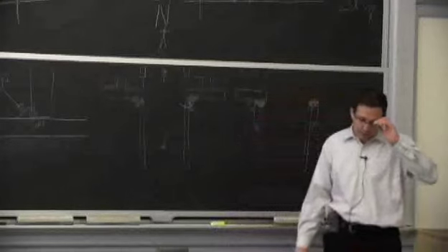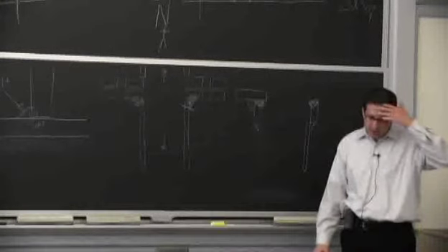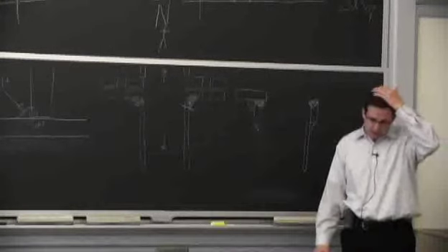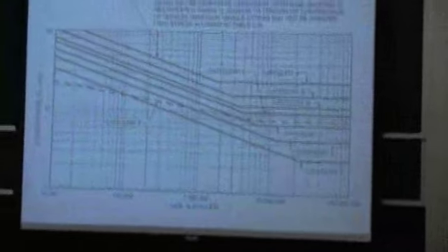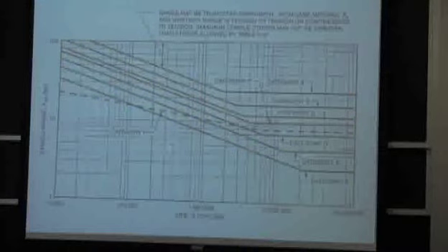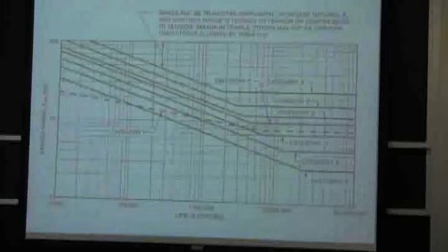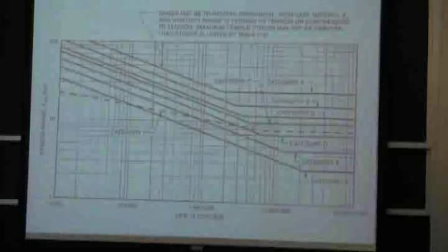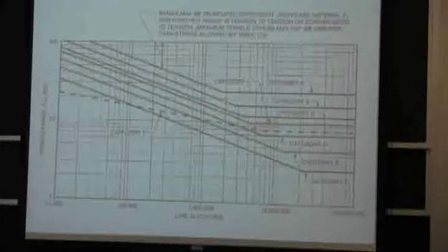But we'll talk about this first standard here, which is used a lot, and we're looking at an SN curve. And this is not a joke. If you're going to use structural steel, this is the AWS D1.1, which in principle is for structural steel. But it's used a lot, even for pipe design and other things, because it's prescriptive.